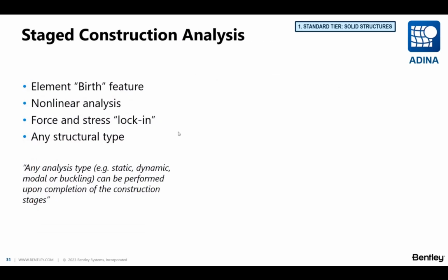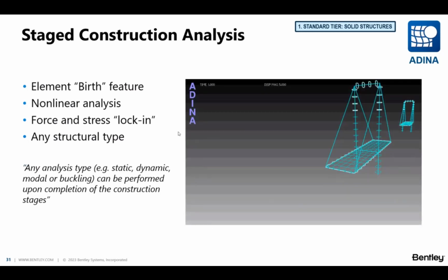The next feature I wanted to present is the stage construction analysis. So we do this via the element birth feature. So elements are born, giving rise to the next construction stage. It's a nonlinear analysis because forces and stresses are locked in from one stage and carried forward to the next construction stage.